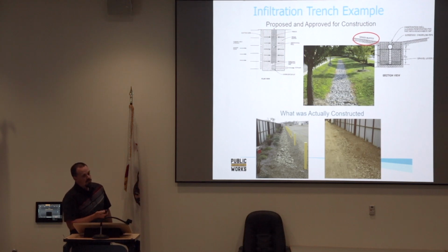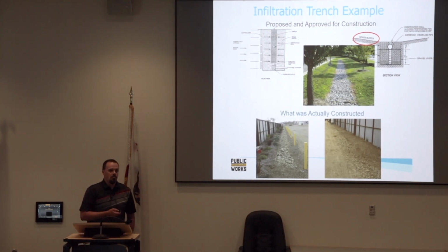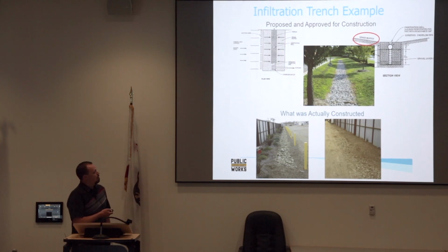So they ended up, during construction, saying, you know what, we're not going to pave this at all. We're just going to keep it dirt. We have some equipment driving around, and to protect it, they put up some bollards to make sure no one drives on it. But right here, it's just going to be sediment impacted, and this whole thing is not going to be functional within a year. One rainstorm, this thing's not going to work.